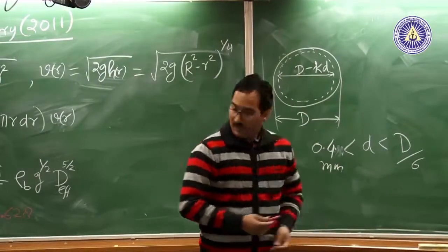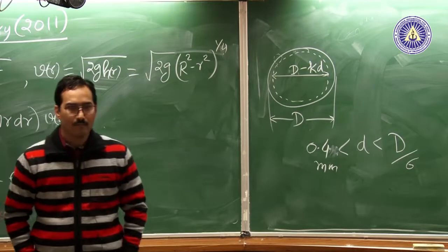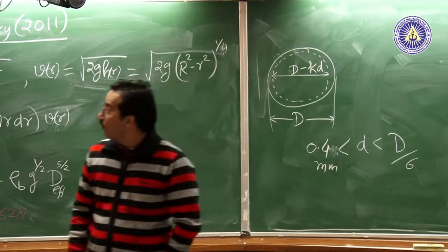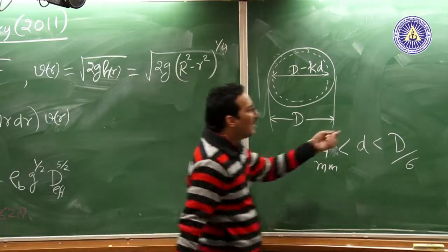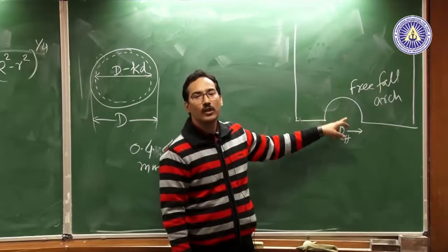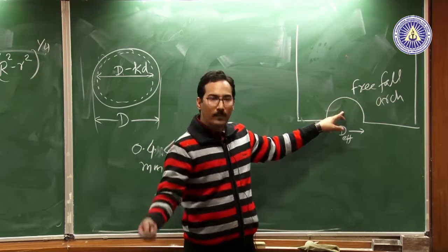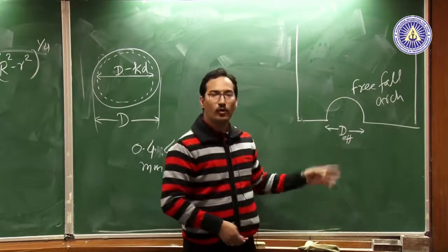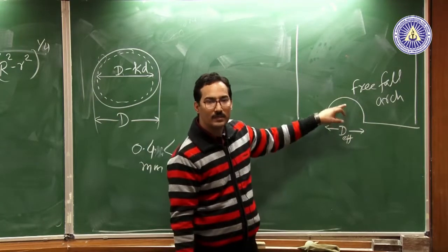All right. So beyond this derivation or supporting this kind of experimental result, does the theory have any other significance? Well, I'll come to that. I wanted to skip that, but since you have said it, this free fall picture has fundamental problems. It says that you have a stress discontinuity at the free fall arch, right? It doesn't make sense. So what people have done is try to disentangle that paradox. People have done simulation, and what you find is if you look at the stresses, your stress doesn't really show a jump here. You don't see a jump in the stress as you would expect, right?